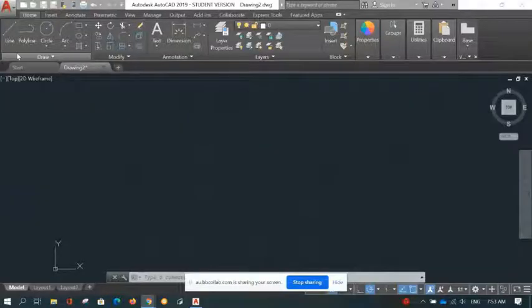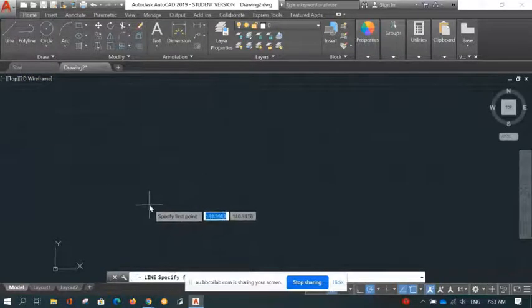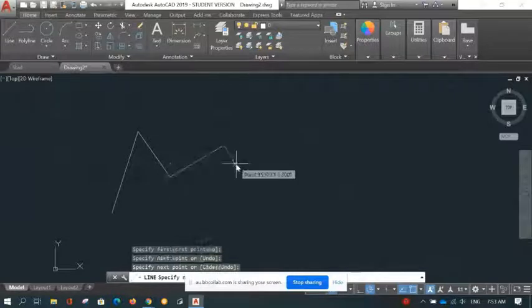I'm going to show you how we will use the dynamic input function in AutoCAD. You can activate the dynamic input by pressing F12 on the keyboard. Example here, let's say we are going to create a line. That's a single line, right? Okay. So the normal cursor will be empty. If you create a line, there's nothing that appears except for the polar tracking or distance.